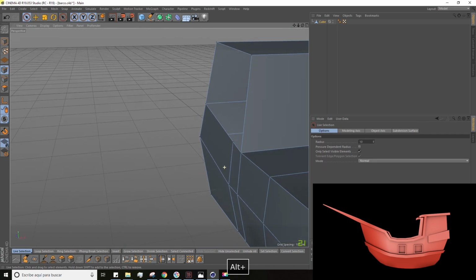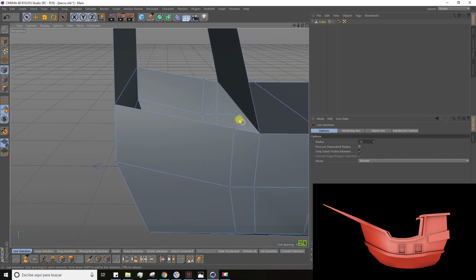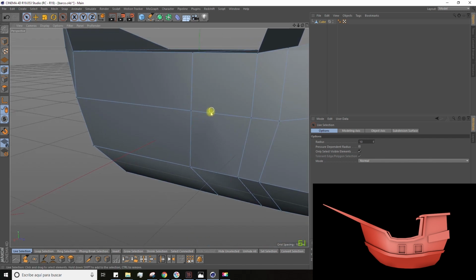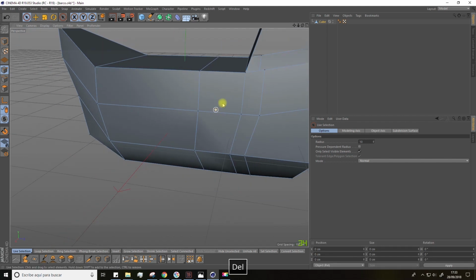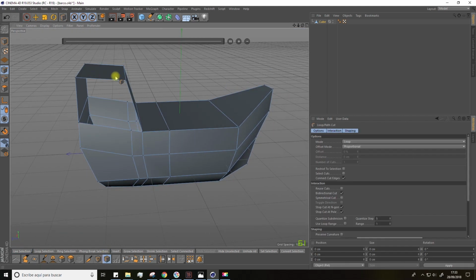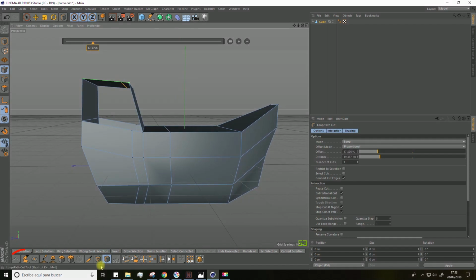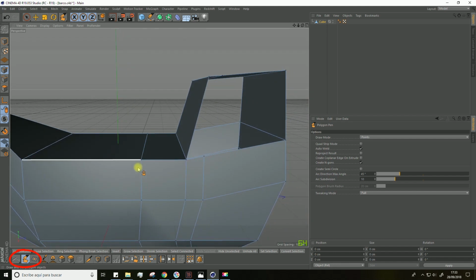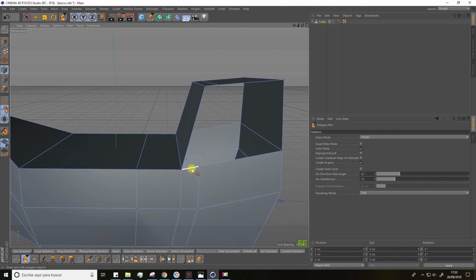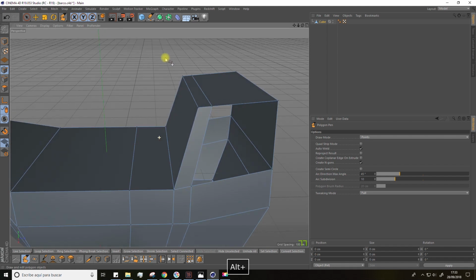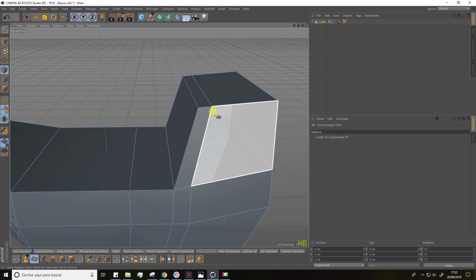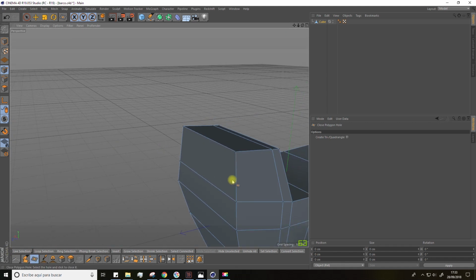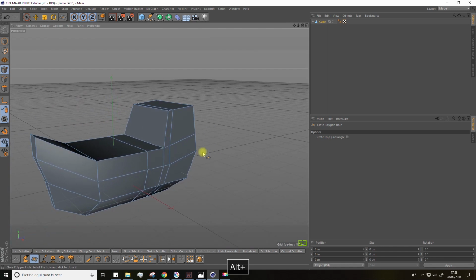If you see that there are leftover points, which might appear sometimes when working with polygons, just delete them. See, we have one here, so let's delete it. Alright, now let's make a new cut here on top. This will allow us to join these points with the Polygon Pen tool. Do the same on the other side. Now, to cover these two holes, we can use the Close Polygon Hole tool. This way, after generating these two polygons, there won't be any hole left on the shape.